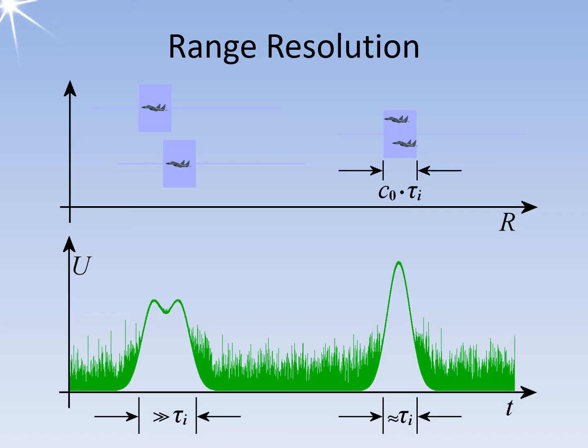The transmitting pulse takes a dimension of c0 multiplied with tau in free space. A 1 microsecond long pulse distributes its energy over a length of about 300 meters in the main radiation direction of the antenna. If two reflecting objects are within this distance, their echo signals run into each other until they merge into a single, but now somewhat larger, pulse. Here, the radar can no longer distinguish whether it represents a target for two reflecting objects or one larger object.